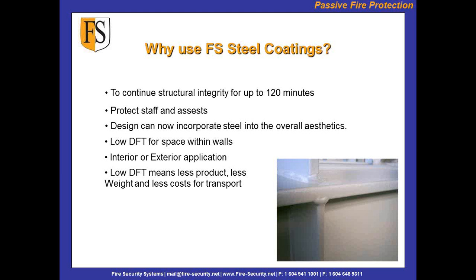You can design and incorporate steel into the overall aesthetics of the building, so the steel can be seen now, instead of hidden behind walls or hidden behind that old cement that you see in the car parks, which is a cementitious-based fireproofing. It looks horrible. It's never finished properly. It's meshed out and very time-consuming, but it's a huge eyesore. But with the thin film coatings, it just looks like paint.